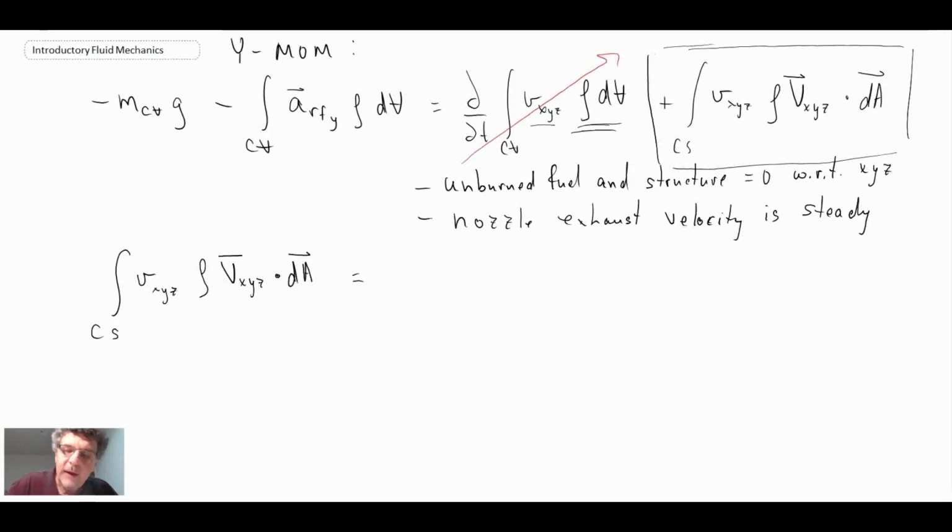So here, the only mass leaving the control volume, or the only place crossing a control surface, is the exhaust itself. And so we have the exit velocity is VE. And if you look at the vector, VE is in the down direction, so I would write minus VE j. And that's why we have a minus for the first velocity term.